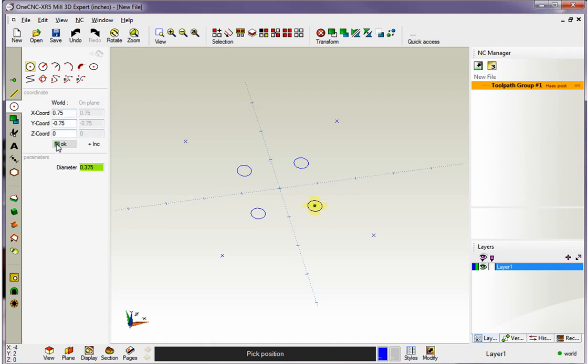Alright, so when creating points, lines, and arcs, just make sure you type in your information here and then click the OK button. Now it is a 3D environment, so you certainly can use the Z value. Let's put this back to X0, Y0, but let's make the Z, how about 1 inch. That looks good. I'll click OK to that, and then as I rotate around, you can see that certainly there's that point that's been created at X0, Y0, Z of 1 inch. Very, very good.